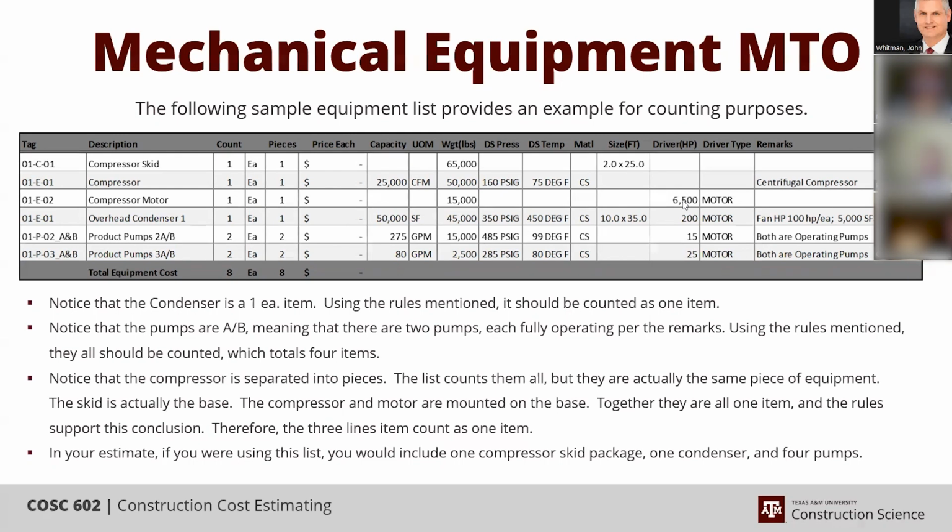And we used to actually, I'm old enough now that a lot of the programs we have today didn't exist. And so I had formulas where, if I knew the pressure and the volume, I could calculate the brake horsepower. And then I knew that plus or minus 30%, we can use so many dollars per horsepower.